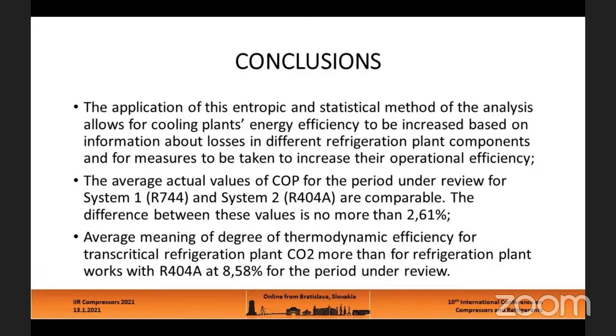The difference between these values is not more than 2.61%. The average degree of thermodynamic efficiency for the transcritical CO2 refrigeration plant is more than for the plant working with R404A by 8.58% for the period under review.